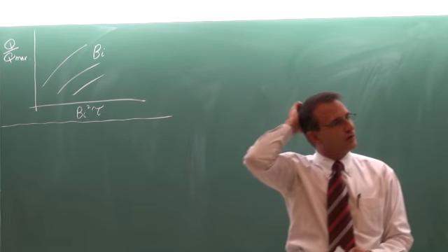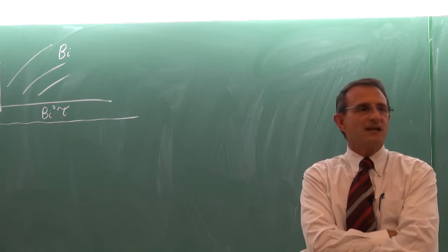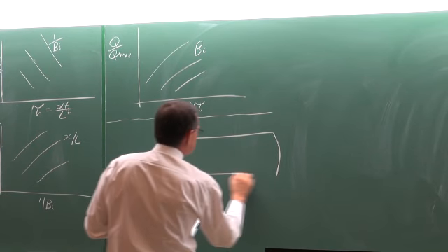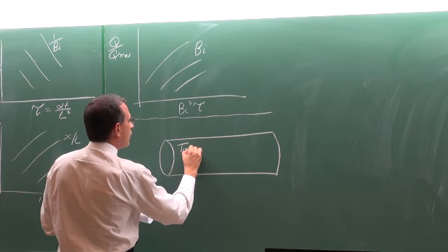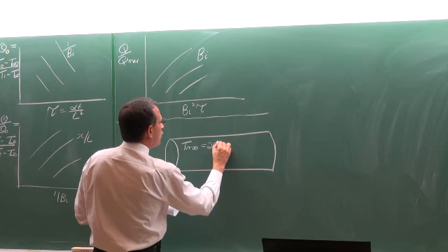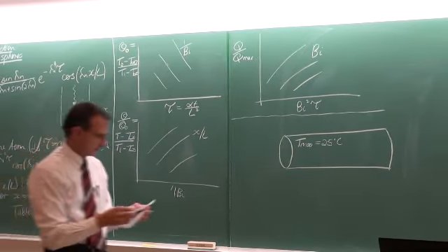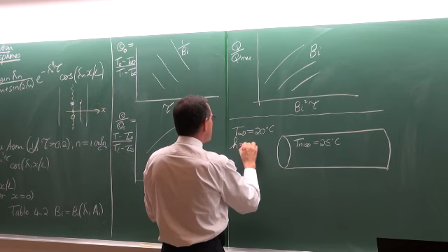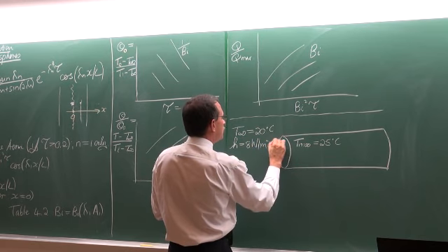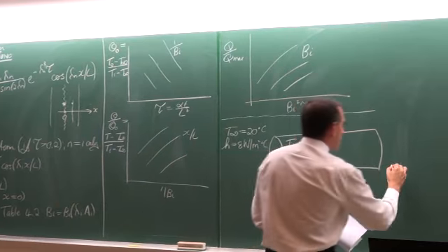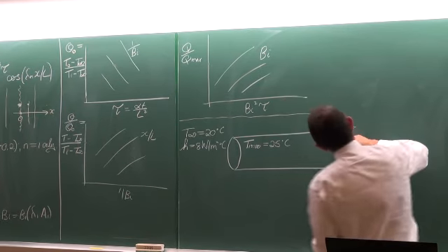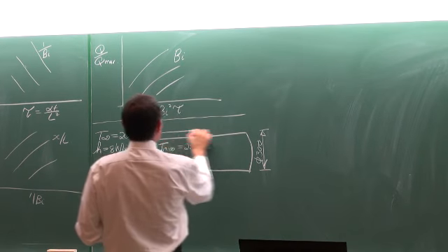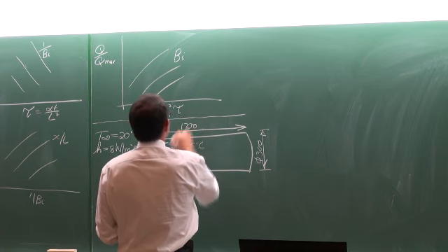In terms of a problem, let's consider the previous problem that we've considered with the lumped system approach, and that is the dead body. The dead body that was discovered at 1700 hours. When the temperature of this body was measured, it was 25 degrees Celsius. It was in a room where the temperature was 20 degrees Celsius and the heat transfer coefficient was 8 watts per square meter degree Celsius. We have assumed that this body can be approximated as a cylinder with a diameter of 300 millimeters and a length of 1.7 meters, 1,700 millimeters.